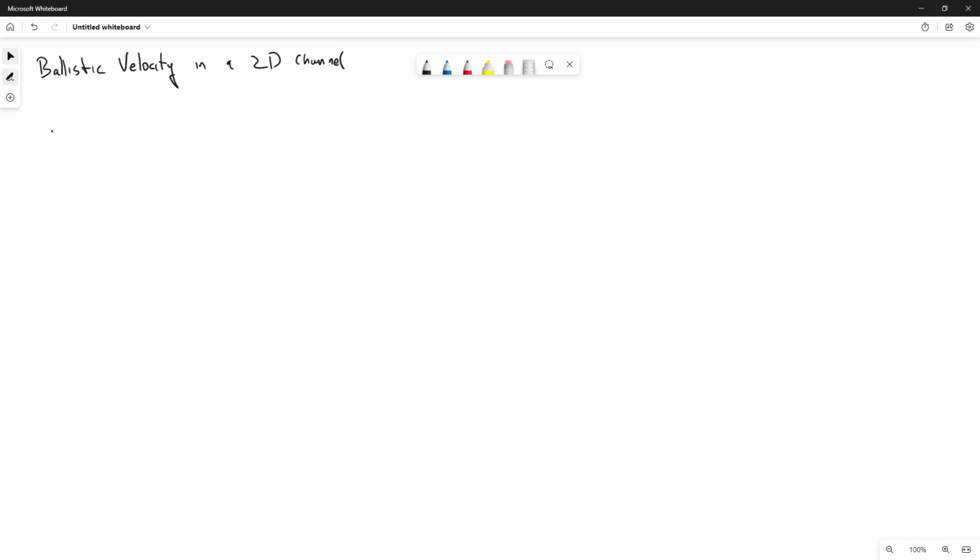Is I by n equal to the velocity, or at least the average velocity? Yes, you have actually derived some sort of equation. In fact, even the transit time derivation comes from this only. Okay, so this is what we do. We essentially divide the current by the stored charge to get a notion of the average velocity.